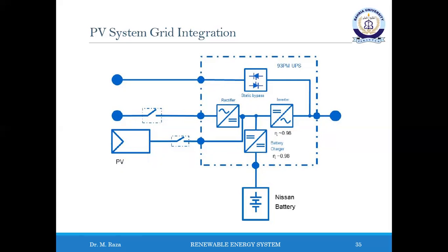A PV panel is inherently a nonlinear current source, and its output power is dependent on ambient temperature and radiation. Based on that, there would be only a few operating points on occasions when the PV source was able to generate power to the load. This means that we cannot achieve the maximum power point in this topology easily.